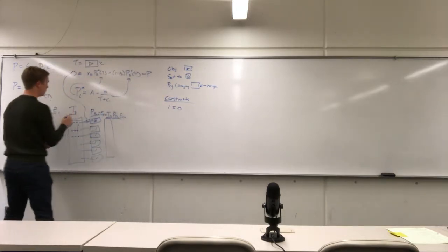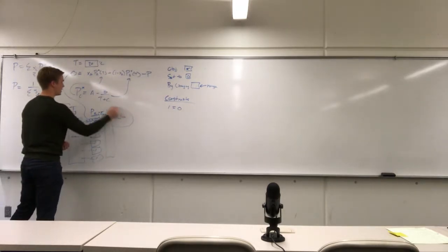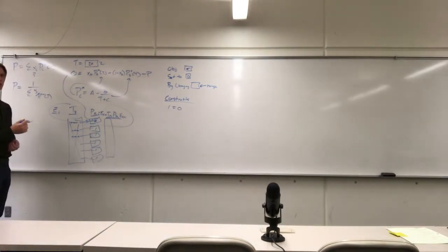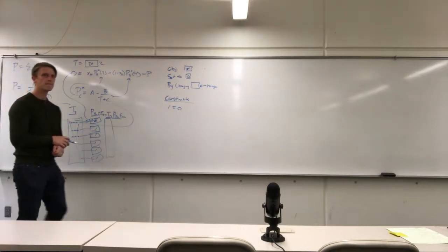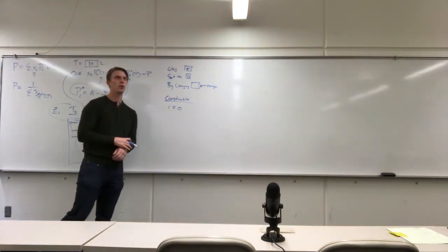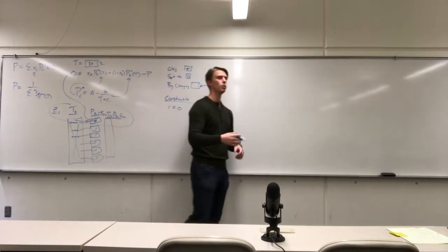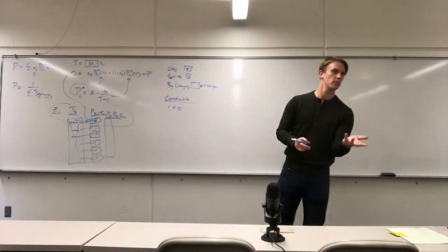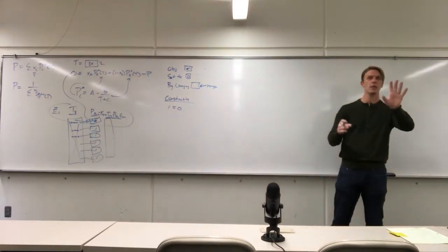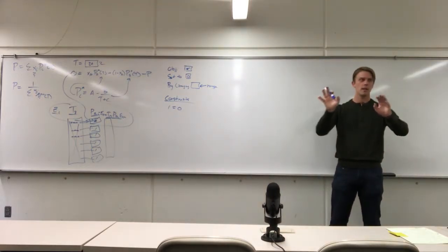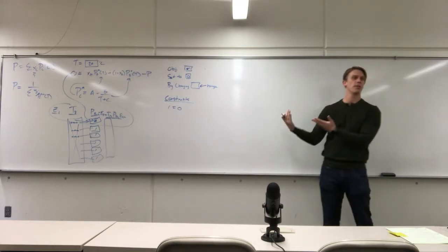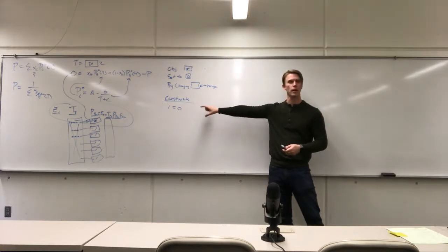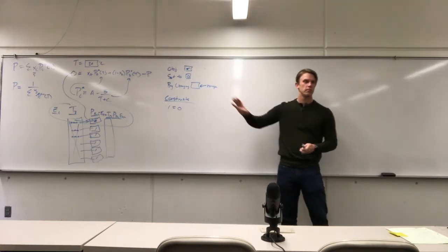So what you'll be doing is you'll be taking your results of the TXY diagram and just plotting your X's versus your Y's. So that will give us our temperatures in each composition at a constant pressure. Yeah. So in the XY diagram, the temperature will be varying, but you won't know what that temperature is. Yeah, okay. But just know that it does change. So if you have an XY diagram and a TXY diagram, based on a certain XY composition, you can know what the temperature is at that point. Okay. But when you create your plot, you'll be basically just cross-plotting.